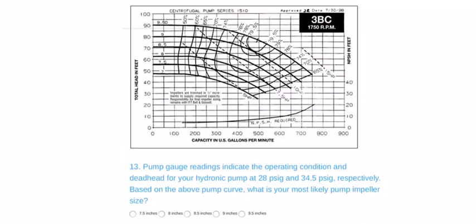Question 13 now has us using the pump curve. One of the typical things we want to do is validate the impeller size on a pump that we see in the field. So the trick here is, one, recognizing which of these values is associated with validating the impeller size and how to convert from PSI to feet of head, which is how we read the pump curve.